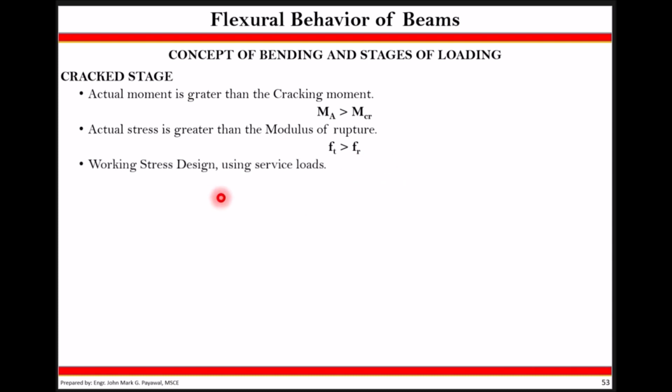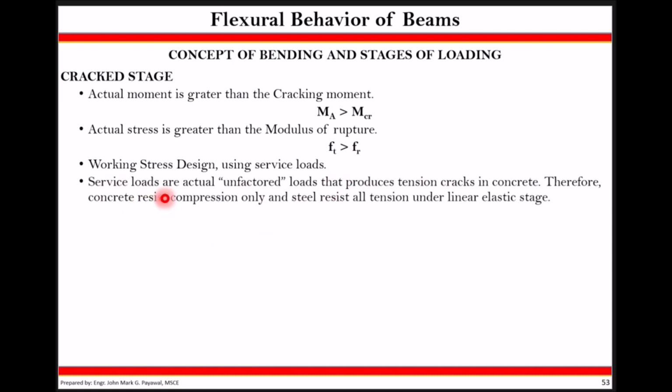Working strength design using service loads. Service loads are actual and factored loads that produce tension cracks in concrete. Therefore, concrete resists compression only and steel resists all tension under linear elastic stage.